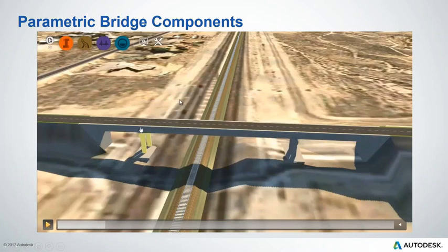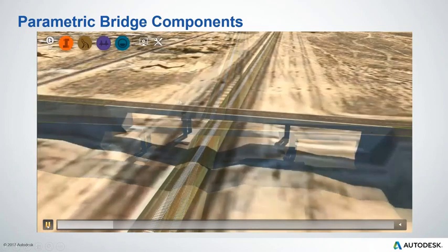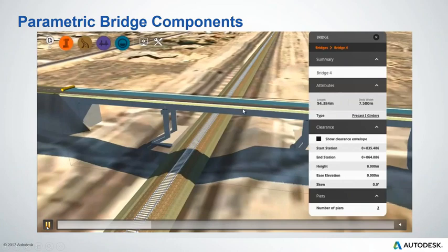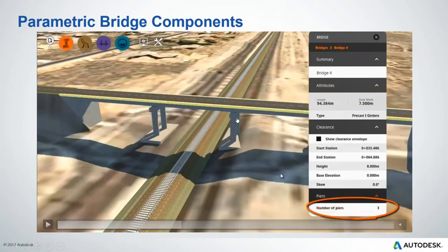As you can see, the deck depth has increased to accommodate for the load and the change in the bridge structure. Not only that, once you zoom into the bridge itself, you have the flexibility of changing everything within that bridge, each and every component. So you select the bridge, and there is an asset card for each and every model or component within InfraWorks. There is what we call an asset card, which allows you to get more information about that component, as well as influence the geometry, the performance, or even the placement of that component within your model.